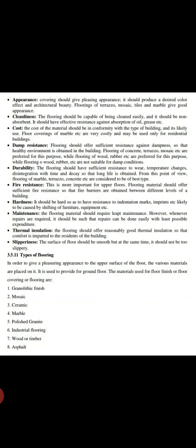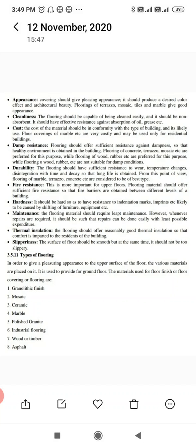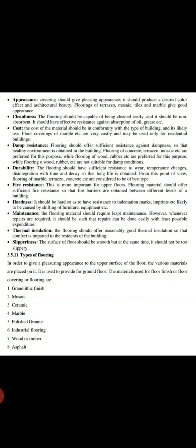Durability. The flooring should have sufficient resistance to wear, temperature changes, disintegration with time and decay, so that a long life is obtained. From this point of view, flooring of marble, terrazzo, concrete etc. are considered to be the best type. Fire resistance. This is more important for upper floors. Flooring material should offer sufficient fire resistance so that fire barriers are obtained between the different levels of a building.